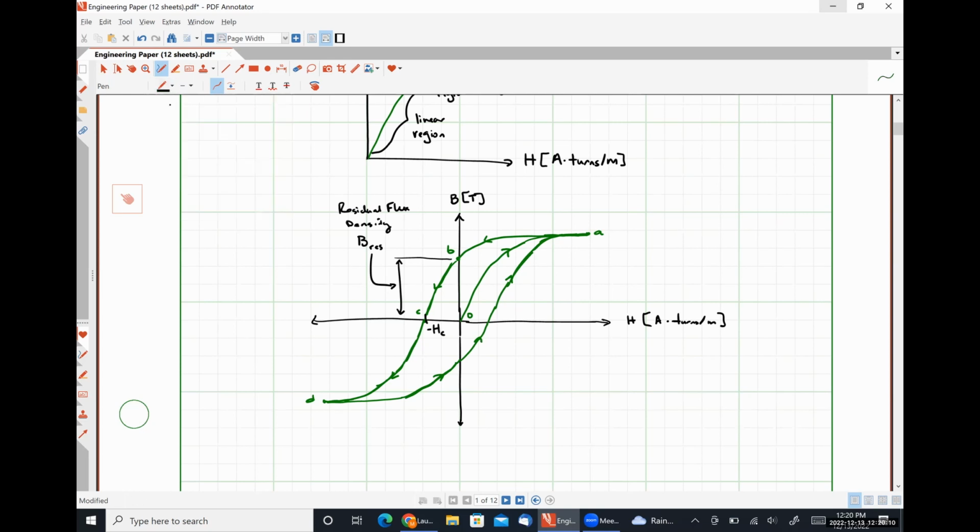So this is an AC magnetization curve, also commonly known as a hysteresis loop. So this hysteresis illustrates a very interesting and important quality of ferromagnetic materials. They have memory in the presence of AC excitation, okay? What I mean by that is their current level of magnetization depends on how they were magnetized in the past.